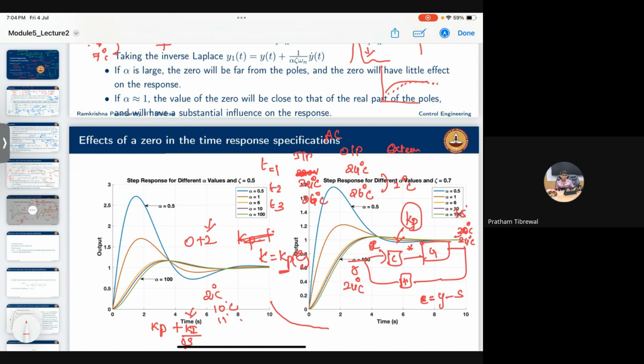At that instant it is changing, right? Based on your error, it is generating proportionally. This is not like that. It will keep track of all the error. If the error has been increasing so far, this will keep reducing it. If the error is getting reduced, this will keep constant. There won't be any change in the integral gain, because the goal is to reduce the error, right? So this is how it will make the error come down as soon as possible. So bringing that error down as soon as possible is the problem here, that it is giving the overshoot.